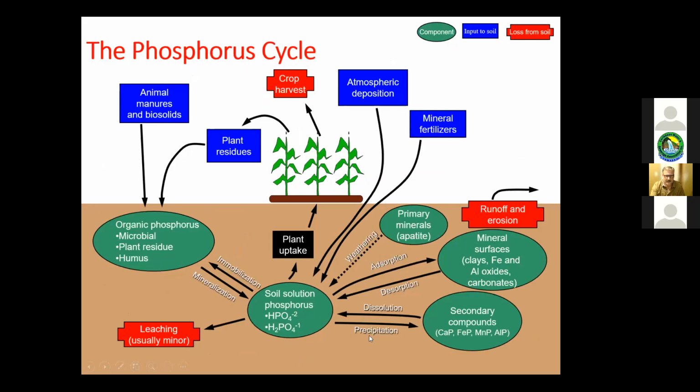There's a phosphorus cycle. Again, it's good to have an understanding of this. Basically, the way we remove phosphorus in wastewater facilities is the BNR facility. You wind up starving organisms at the beginning of your process. Now they want to survive, so they're running around trying to find oxygen, they're trying to find food, and they will actually dump a portion of phosphorus from their cellular membrane. And then as they move through the system, you can think of it as they actually grow a little bit. As they grow through the system, they wind up taking up more phosphorus than they released. When you waste from your mixed liquor tanks or your bioreactors to keep your suspended solids where you need to be, then you're getting your phosphorus removal.